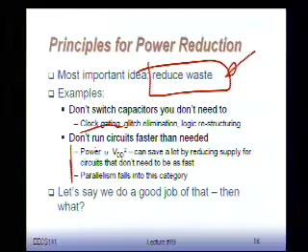So power is proportional to VDD squared. If I'm too fast, lower the supply voltage a little bit. For example, you can actually make it even slower by sometimes doing two things in parallel. There's a couple of games you can play to reduce power. And then finally, there's transistor sizing.